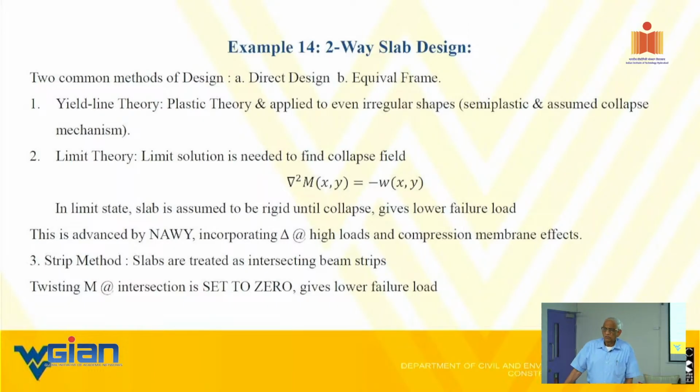Over reinforced, it will be from the concrete side. He's right. Then that is what he is asking. Even though it is over reinforced, the failure will be at the concrete side. Correct. Then why are we getting it over reinforced? Then we don't have to test to determine the FRP properties for an over reinforced beam. Instead of over reinforced, we can increase the strength of concrete.